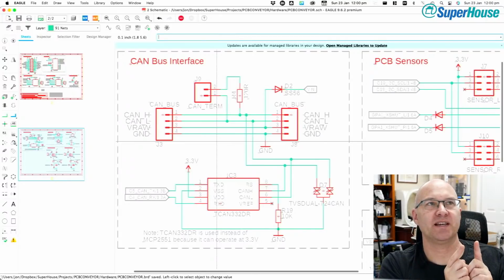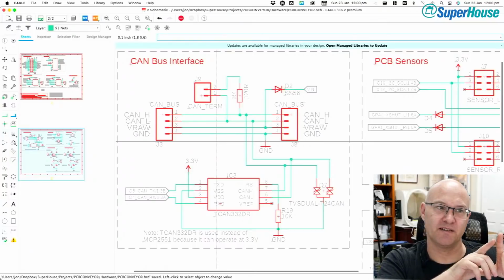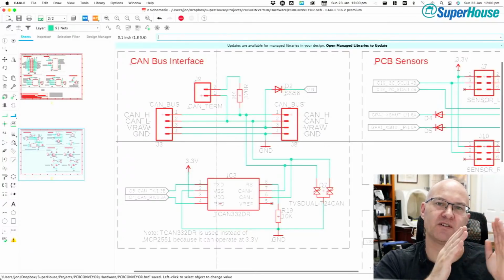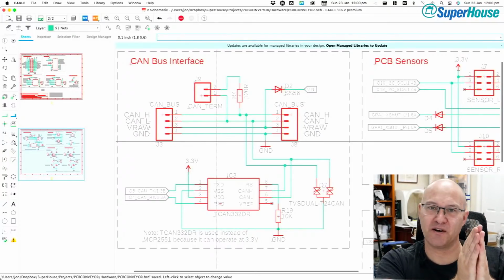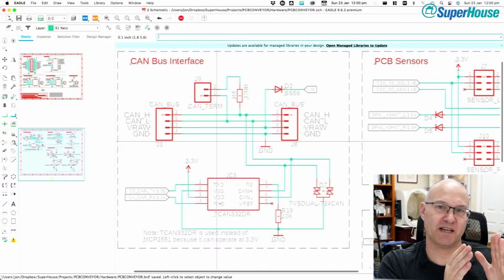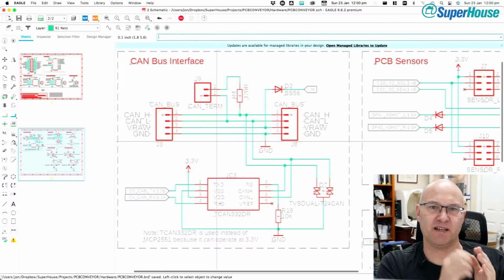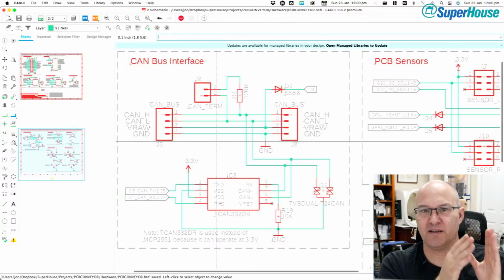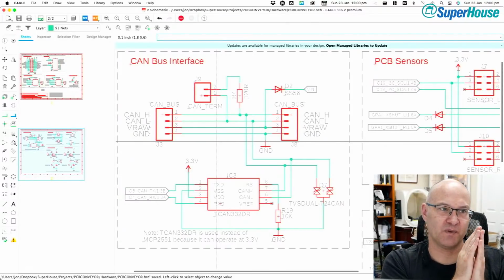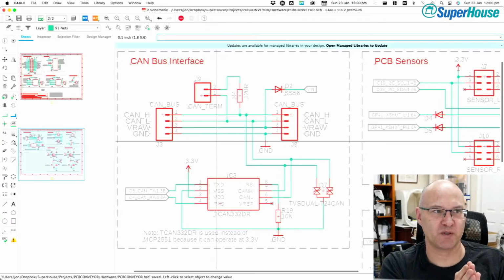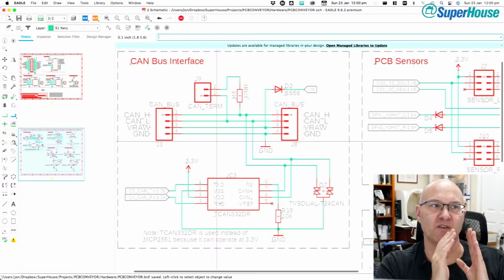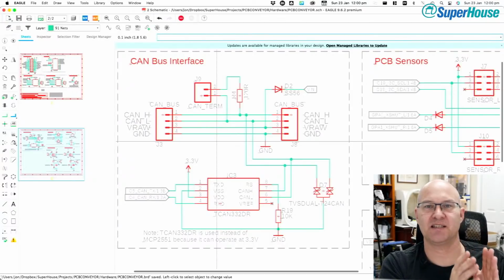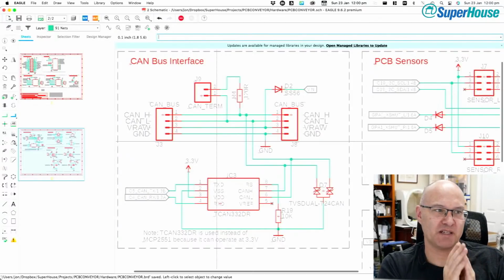If one of those relays fires a fraction of a second before the other, like it's just a little bit quicker, the contacts close. Those contacts are then carrying the full current briefly before the other contacts close. And so you can get arcing and degradation of those contacts over time. Now I'm talking about an electromechanical system there, but the general principle is if you're wanting to switch power, it's best not to parallelize things to get the current rating you need. It's best to use a thing that is rated to the current you need.